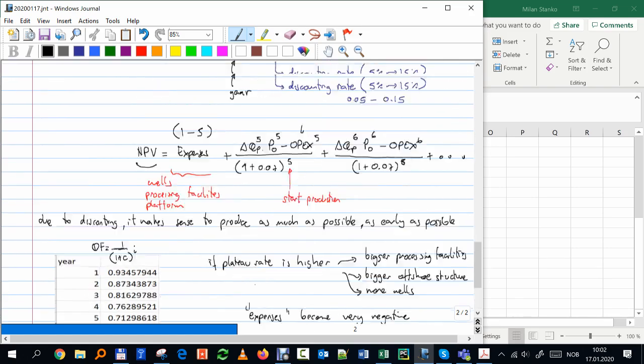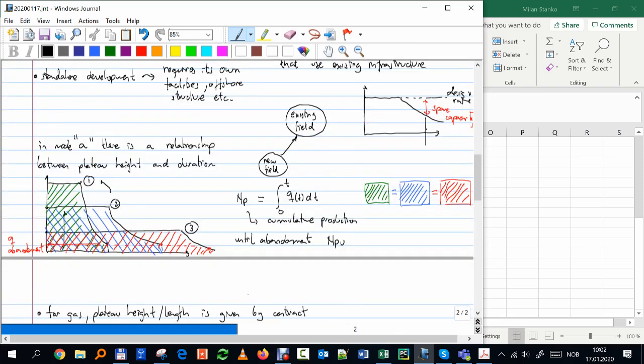Let's say you were going to produce one particular field, a light oil field. You would produce it with a very high plateau, but you have a neighboring field which has very poor API or some H2S characteristics, so you cannot sell it at a good price. In that case you might decide simply to lower the rate and produce less, just to make sure you have a good ratio, such that you produce both fields for this time. You produce at the end the same volume or higher volume, but you can sell it at a better price, or maybe more refineries will accept it.